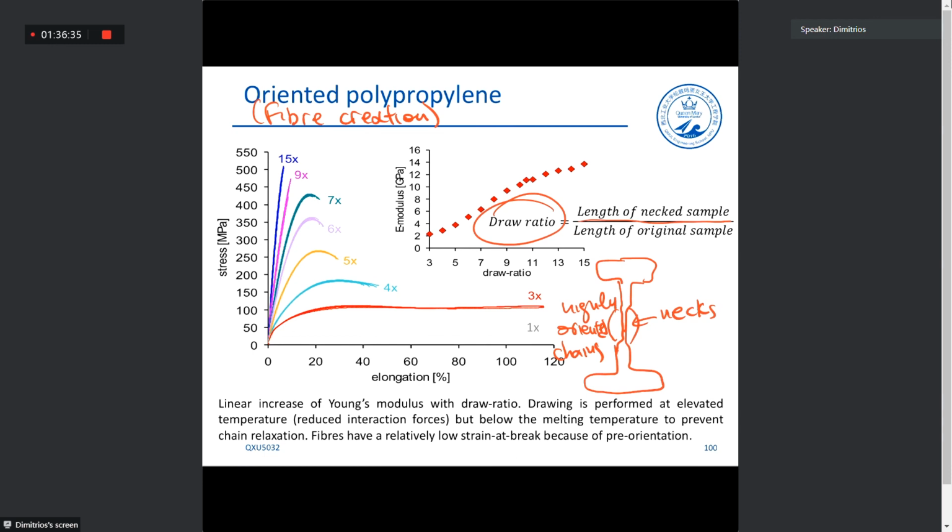Also, there are some parameters that can significantly affect the measurements of our mechanical properties, and these are both the temperature and the strain rate, how fast essentially we're pulling and at what temperature we're pulling. At increased temperature, as you can understand, the chains have a higher mobility, and because of that high mobility, they're able to slip quickly against each other, and that softens the material. They are closer to their rubbery state, and that leads to a reduction of the modulus, a reduction of the tensile strength, and an increase of the strain at break, as you can see for PMMA.